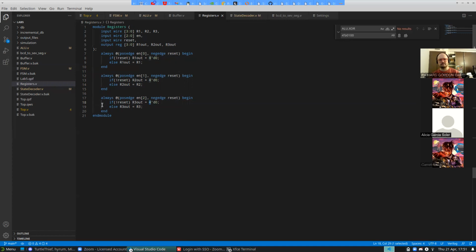This is all pretty simple. The only real difference between a flip-flop and a register is that the flip-flop happens on the edge. So the data is passed across the flip-flop only on an edge. So you need to make sure that you're always setting the enable signal back to 0 when it's not in use. Because otherwise it'll take 2 clock cycles because you'll have to set it to 0 and then set it back to 1 to trigger that edge again.